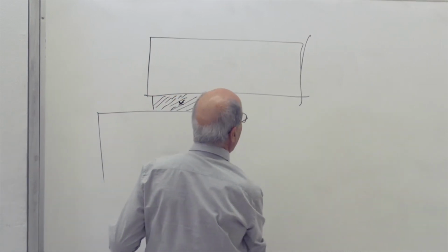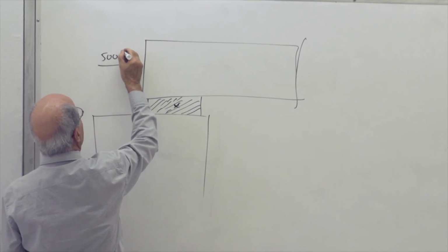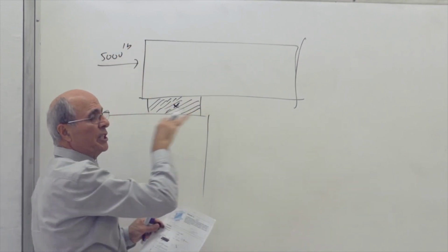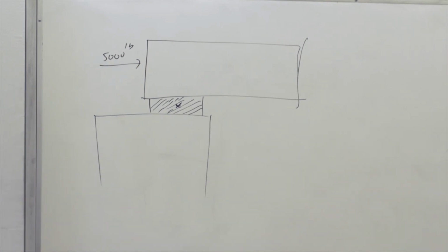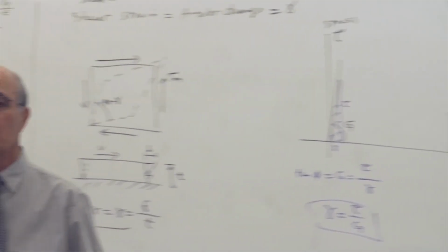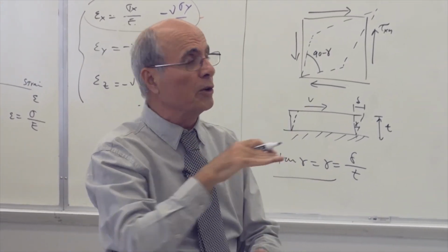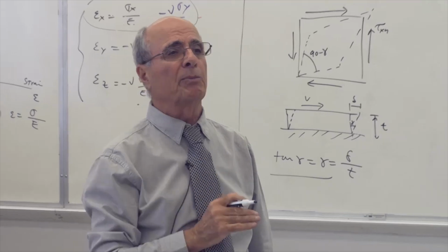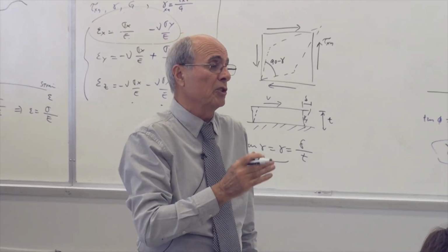I'm going to show the dimension of that one. There is a force here, P equal to 5,000 pounds, applied to this. You see the action of the temperature, the action of the earthquake, the action of the truck braking, or everything causes horizontal force. Horizontal force causes the beam to want to move on top of the concrete, and I cannot put steel or concrete over the concrete. Everybody, concrete over concrete is the worst.